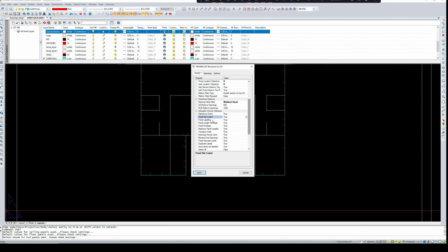It can be used to provide the bracing. Panel labeling: each panel has to be provided with a label and a length. Panel length shortage: if any panel is going to be short, then there will be panel overlap. Panels should not overlap. The panel size should not exceed the maximum panel length. We have set a transport limit, and it should not exceed that as well. Say a panel should not weigh more than 80 kg or something like that.